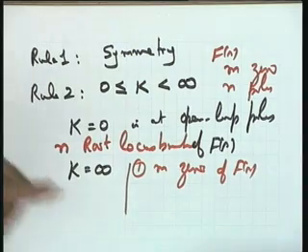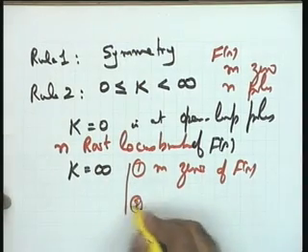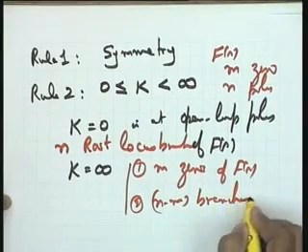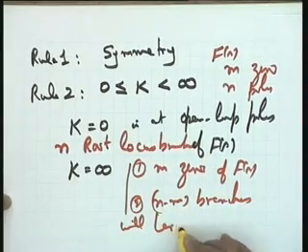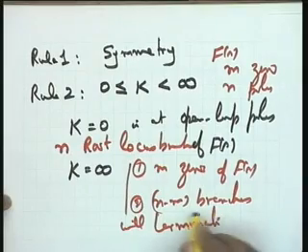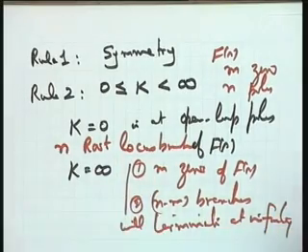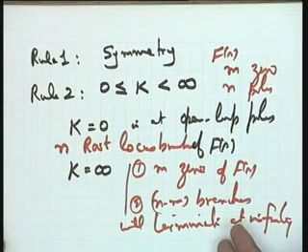How about the remaining n minus m? The n minus m branches will terminate at infinity. In which direction we will see, but they will definitely terminate at infinity. You have to absorb these rules. The proofs are very simple, but I am just saving time.